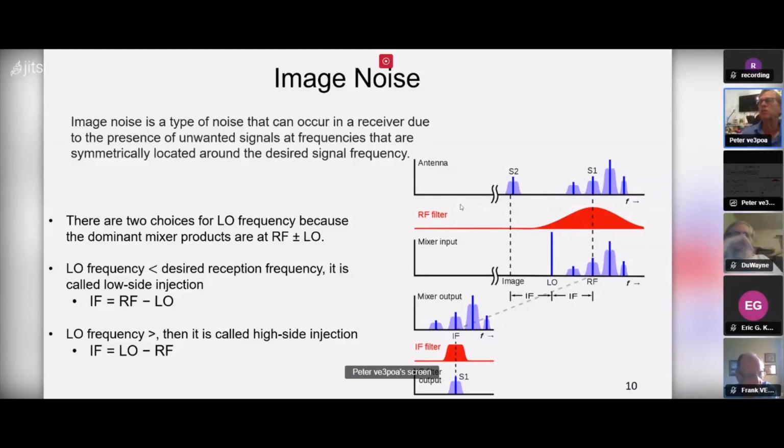And then there's just a quick diagram of this is what your antenna is receiving in there. Then your first stage of filtering, and you're basically filtering out where your image frequency would be. Your mixer outputs here with all those frequencies in here, then your IF filter is tight enough that it rejects it all, and you're left with just the frequency of interest.